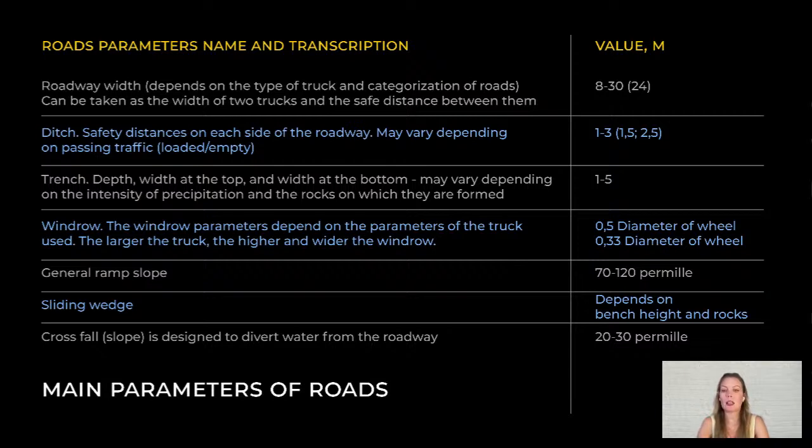Rock barriers can be made from soft or hard rocks, affecting their dimensions like the bottom width. The height of these barriers depends on the vehicles. For heavier vehicles, it's typically half the wheel diameter. For smaller vehicles, like those up to 40 tons, about 1/3 of the wheel diameter. The slope of the exit road is also a major economic factor. A longer road means more distance for transporting rock, which means increasing costs. However, too steep a slope reduces transport speed and efficiency.